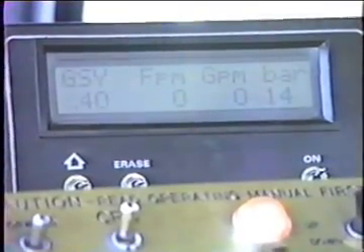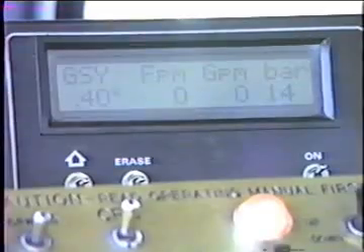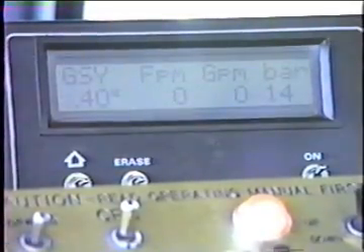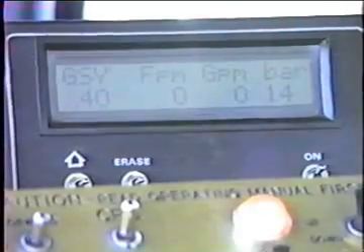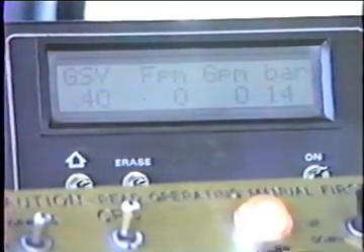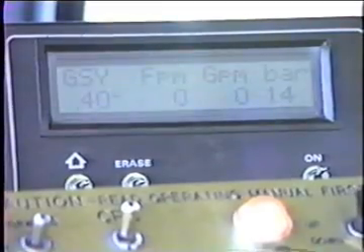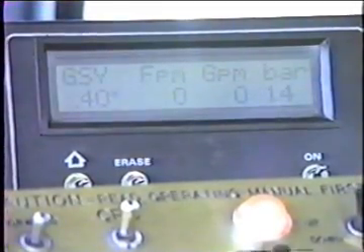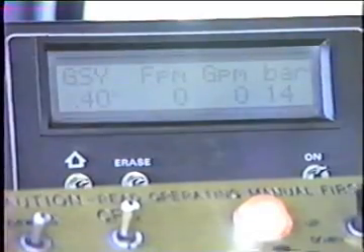The computer will adjust the asphalt pump to the exact right GPM to satisfy the instantaneous current conditions that it sees, that is desired spread rate, travel speed, and bar width. If we change any of those things, the computer readjusts the asphalt pump to compensate. And we can change anything.